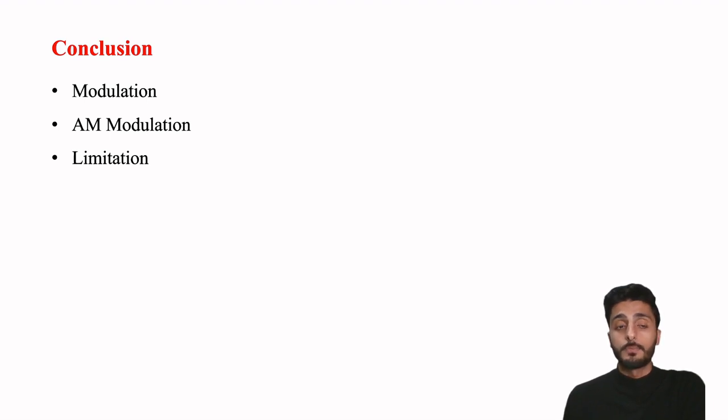We saw the modulation operation and what is the main modulation equation, and we saw the shape of the modulated signal. Then during the MATLAB implementation, we saw the limitation of the amplitude modulation and how the system has no immunity against noise, because simply the information is modulated on top of the carrier signal amplitude, and any variation in the amplitude because of the noise will affect the received information. And finally, you can modify and experiment with the MATLAB code to further enhance your understanding of the system.